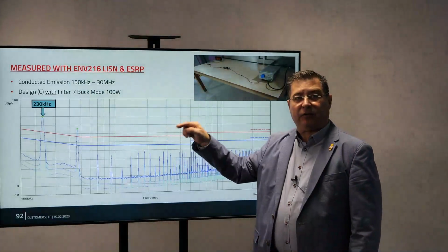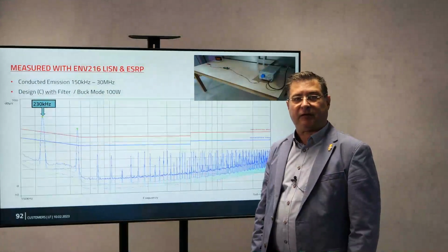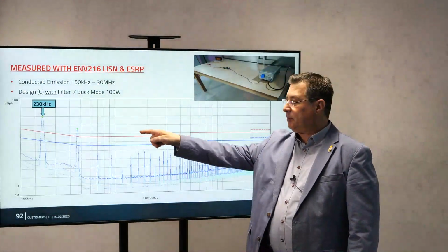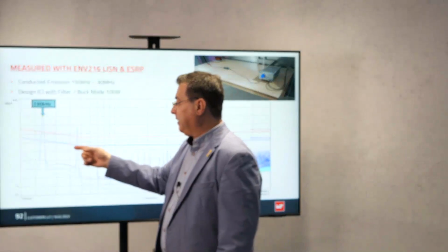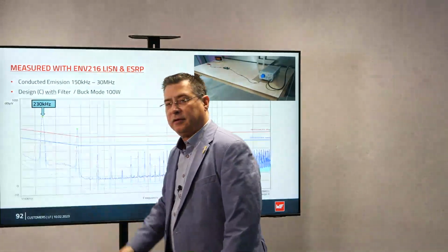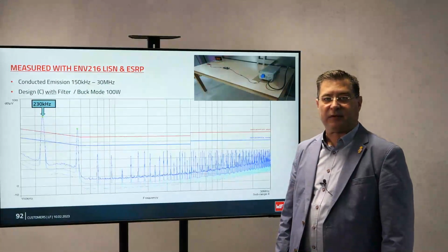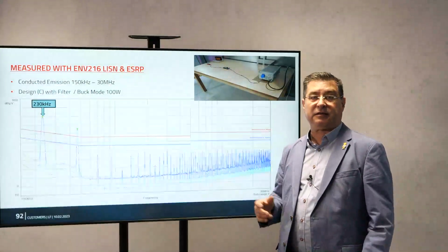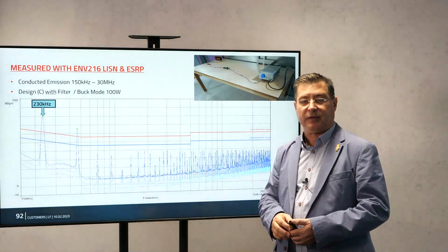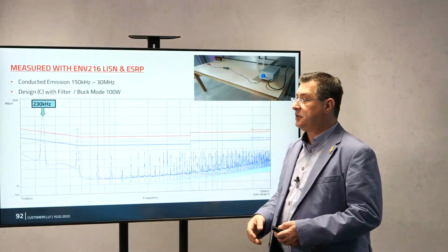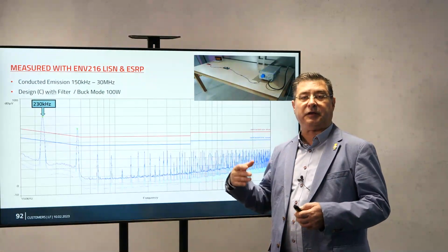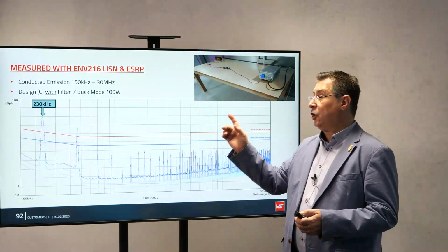The 1 microhenry inductance should be there, because this is responsible to attenuate and to filter these harmonics. It needs to be there because otherwise I will not pass conducted emission. Now, I'll go with this design to the anechoic chamber and make the EMC radiated emission, no filter.